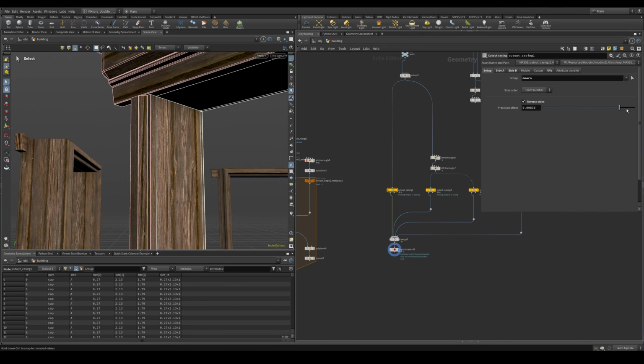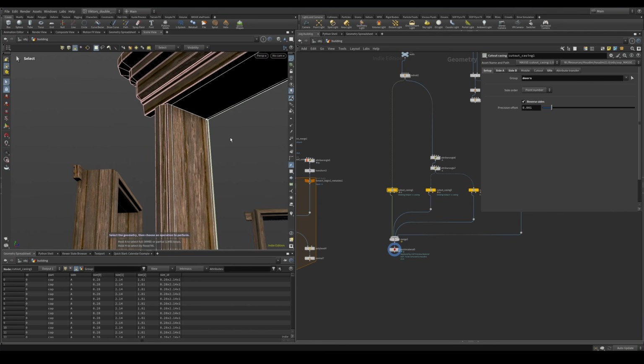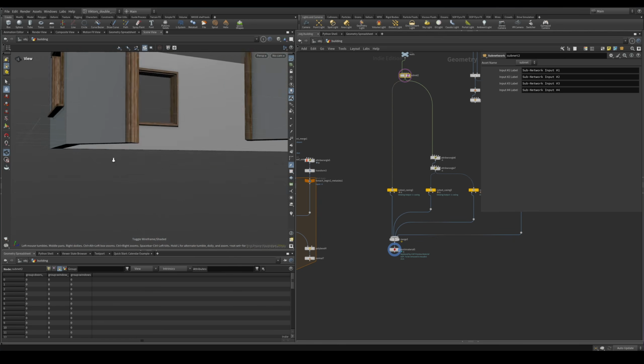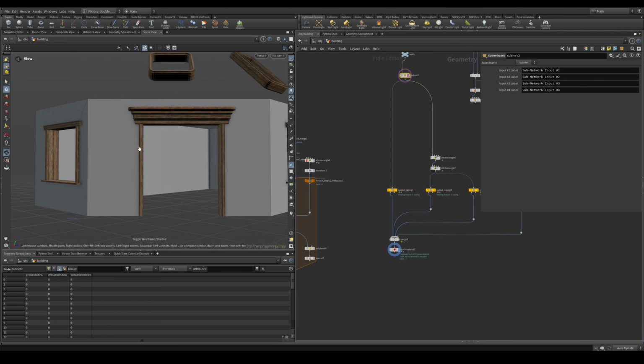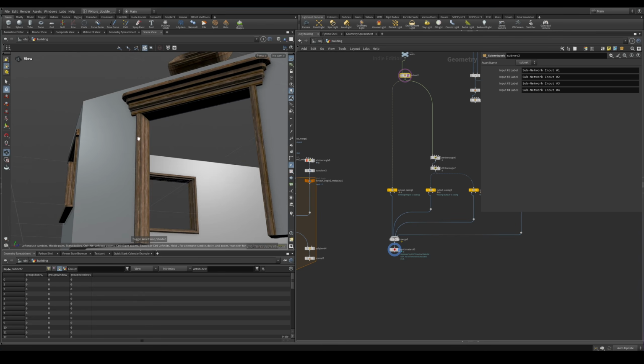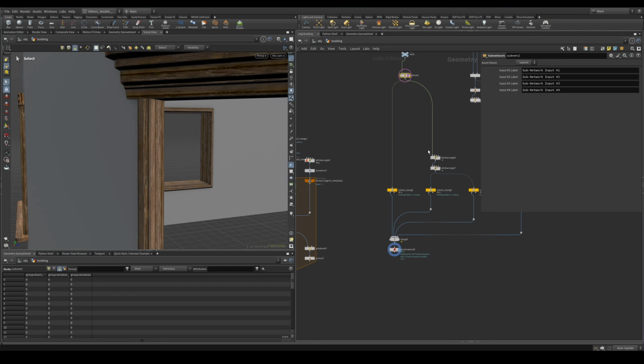You can see if you start to move it, you will notice that casing goes very slowly inwards. So this shouldn't really be a very big value, because you want to make sure that the casing is at the location of our original source side, but does not intersect with the original geometry.